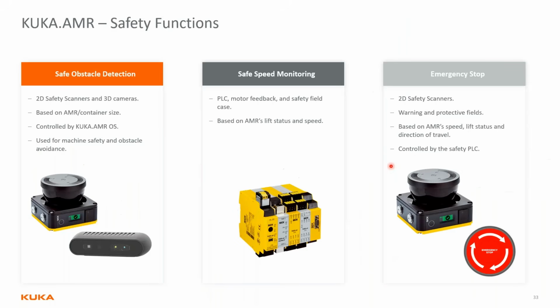So KUKA AMRs have different safety functions. There is safe obstacle detection, which uses the 2D scanners, 2D safety SICK scanners, and 3D cameras. And I want to mention here that the 3D cameras are not safety rated. The SICK scanners are safety rated, the 3D cameras are not.